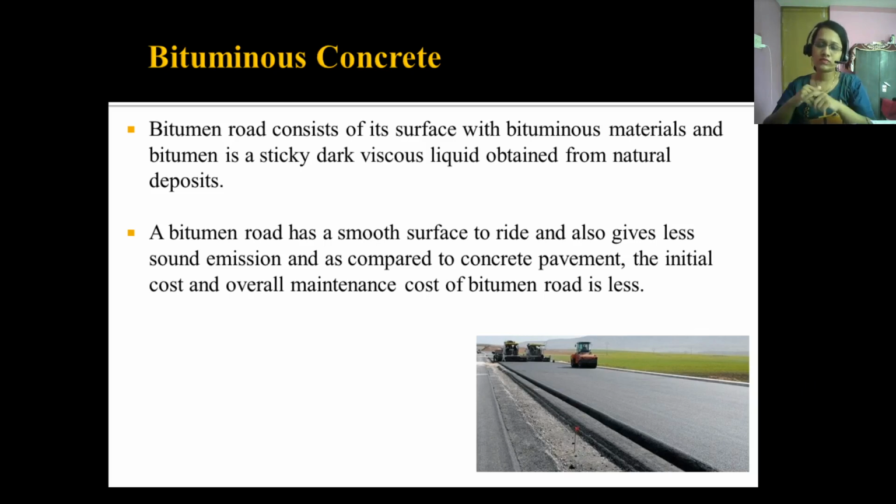So it is possible to construct relatively thin bituminous pavement layers over an existing pavement. Therefore, these are commonly adopted as a wearing course. Flexible pavements could be strengthened in stages by constructing the bituminous pavement layers one after another in a certain period of time, unlike the cement concrete pavement construction.